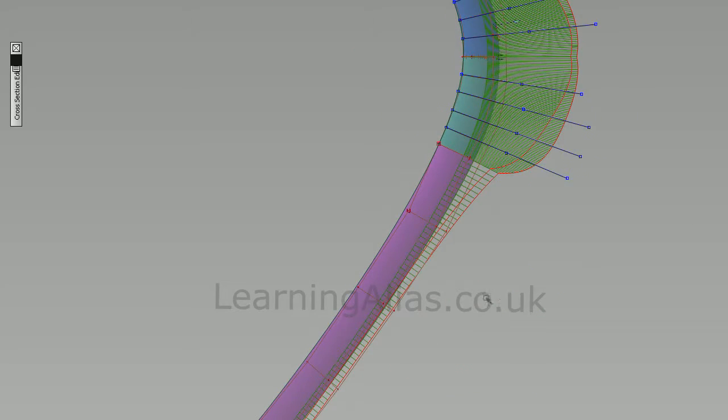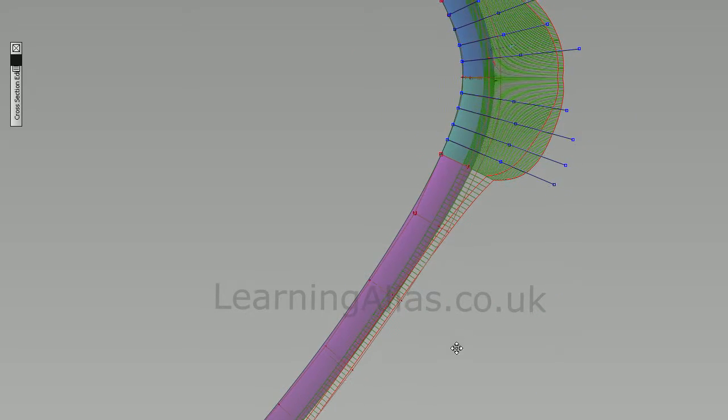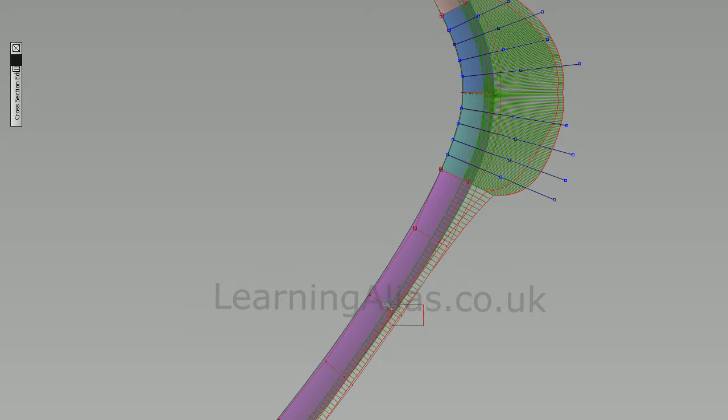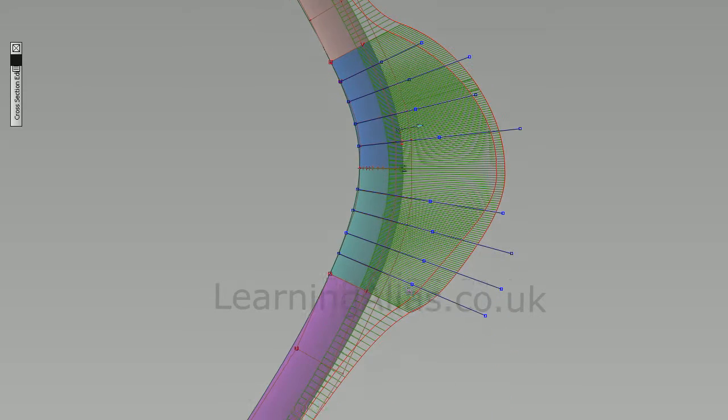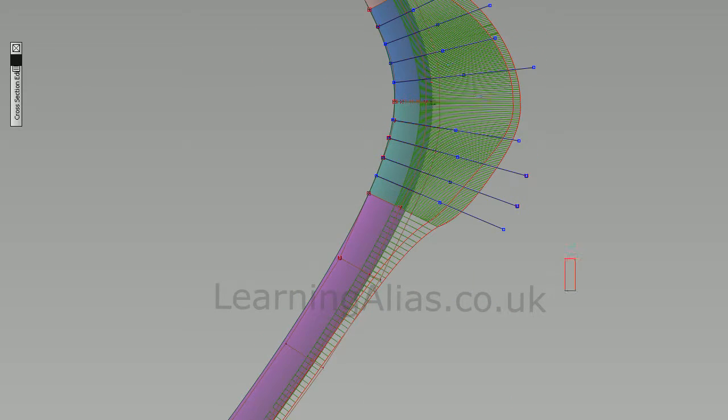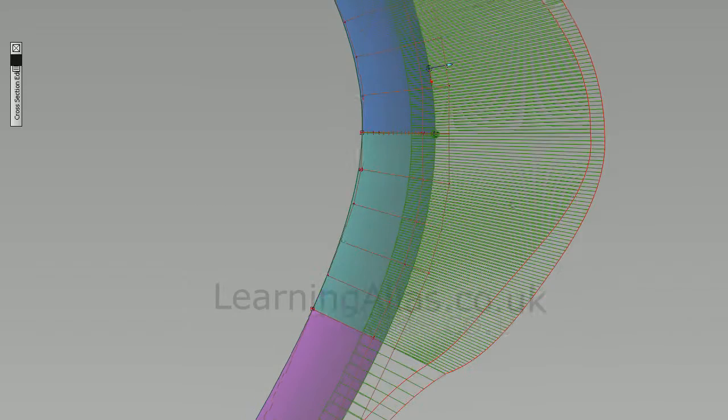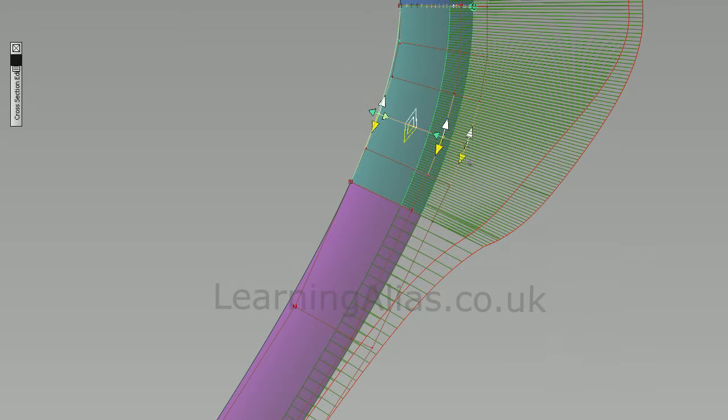so we're going to use the same technique to just tweak these CVs, and it's best to go back and forth between surfaces that are going to have influence on one another. Don't try and sort everything out in one surface. So I've gone ahead and put some more time into tweaking the CVs. You can see we've got a much more even curve on our comb, a nice crown, and closer to G3 continuity. I'll get rid of the helper curves and we'll do a bit more tweaking.